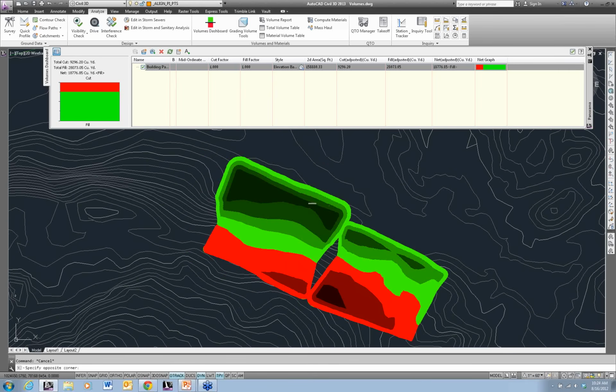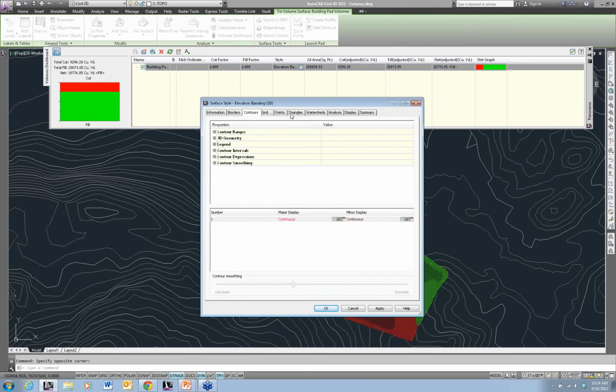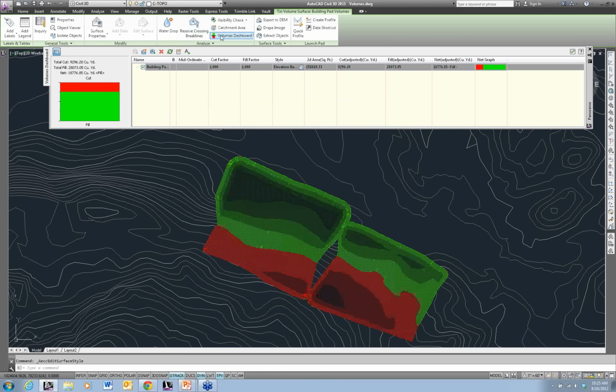If you go to the style of the surface, so if I edit the surface style, under the Analysis tab, under Elevations, you can choose the color scheme. In this case, you can see I'm using the rainbow scheme, and that's what Kelvin commented, use the rainbow. So if you try some of the different ones, maybe they'll come out differently. I'm not exactly sure, honestly. Let's try one. So let me go to the blues, just because it's different. Oh, wait a minute. Is that something that I...